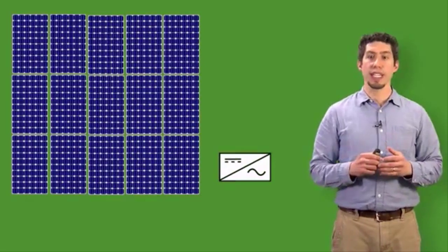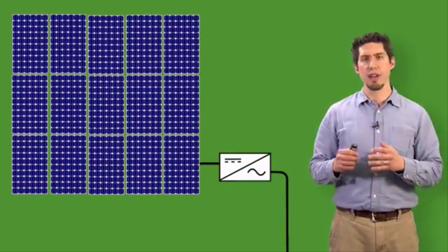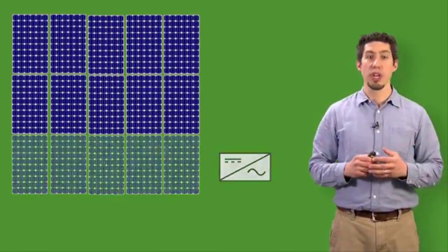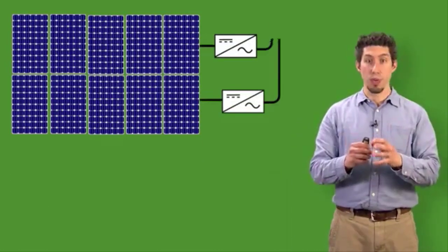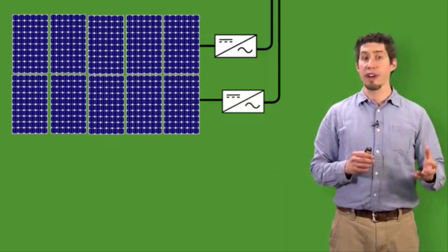There are several types of inverters that are available. Larger inverters can accept and convert photovoltaic electricity from about 10 to 80 modules. You can also have multiple smaller inverters in one large installation, serving only 5 to 10 modules per inverter. In all cases, you need some sort of monitoring system to both quantify the amount of electricity being produced and monitor the electrical grid connection. Monitoring the electrical grid maintains frequency parity and allows response to mandated shutoffs, like when there is no grid electricity present. These inverters are designed to handle multiple solar modules.